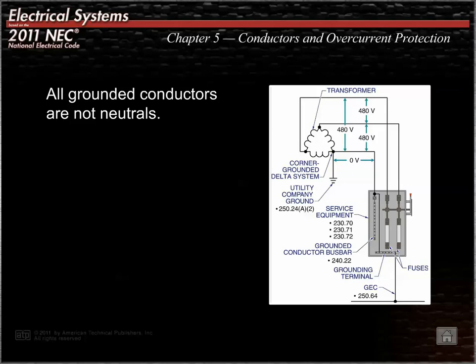In the majority of electrical systems, the grounded conductor is the neutral for the system and carries the return circuit current. For this reason, the grounded conductors, in general, are not provided with overcurrent protection. There are, however, two exceptions to this general rule. The first is for installations in which all the circuit conductors are opened or disconnected from the supply simultaneously, and the design is such that no pole can operate independently from another.